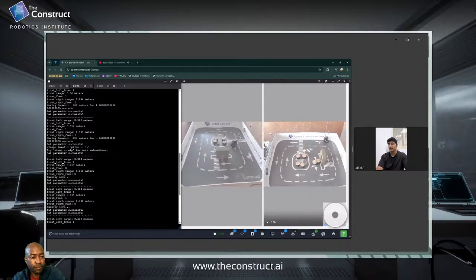Yes. And the threshold, which has been set as 0.3, if it meets that criteria, it's going to stop and look for the next plausible area to move towards, if it's free. If all areas are blocked, essentially it just stops and stands still because there isn't any safe place for it to carry on its patrolling.